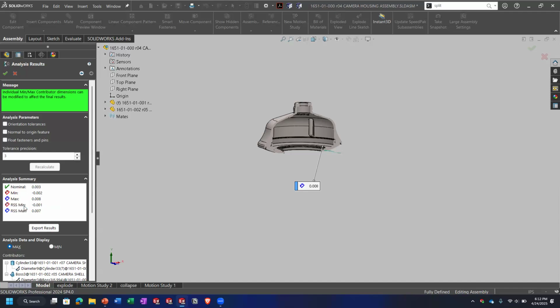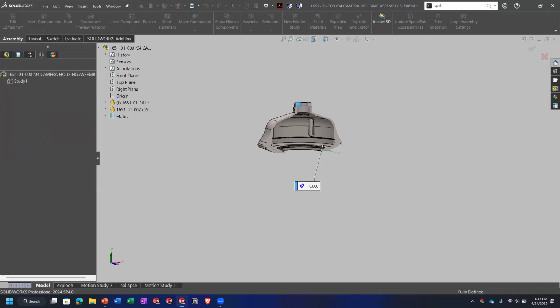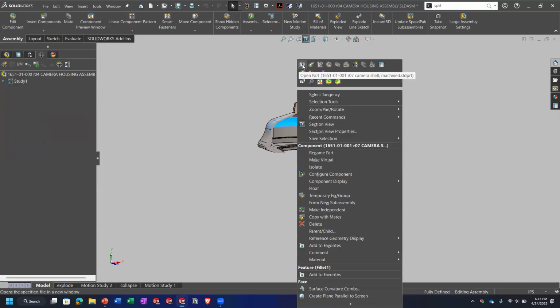And the root sum squared, if you're not familiar with it, is essentially an analysis to tell you, in this case, I believe there's one, oh shoot, I just forgot the term. Well, basically it's telling you that on average, 60% of the time your parts are going to be within these dimensions. So even not worst case, most of the time my part could be within a bad tolerance there at -1 thou. So that's where we should probably go back and fix that.